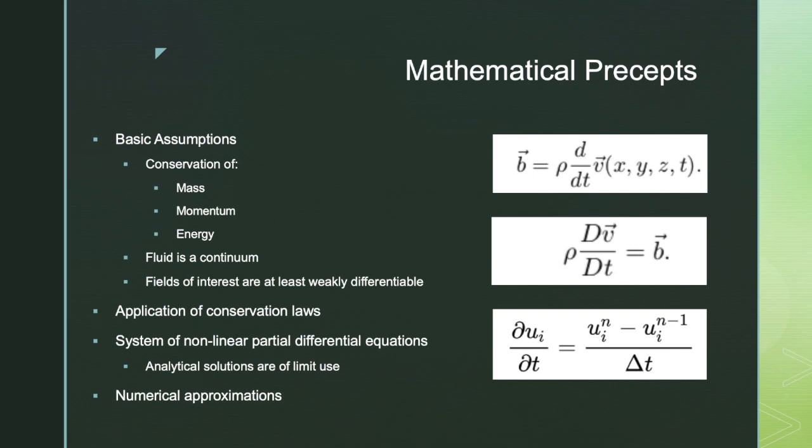The derivation of the Navier-Stokes equations involves many different mathematics and physics concepts. Some of these concepts are the Reynolds transport theorem, the divergence theorem, and the Leibniz rule, which are all used in the development of the conservation law for an intensive property. The derivation of these equations also involves the use of Newton's laws of motion, the material derivative, the chain rule, gradients, and stress tensors, all of which results in a system of nonlinear partial differential equations that, as previously discussed, are very difficult to solve analytically.